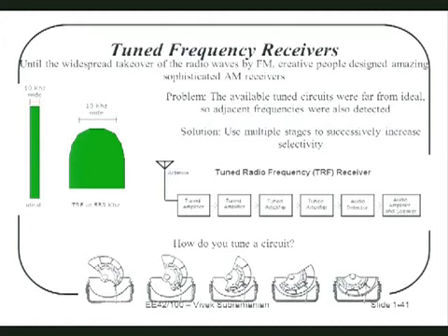Yeah, that's perfectly good. I would take some insulator, like a ceramic, and I would slap an aluminum foil on the top and the bottom. That's a capacitor. A capacitor is 2 conductive plates, for example, separated by an insulator. Okay, what sets the value of the capacitance? I've taken that sandwich of 2 aluminum foils separated by a ceramic, and I want to know the capacitance. What sets the value? Correct. The capacitance value is set by the surface area, namely how big those aluminum foils were, and the spacing, and one more thing.